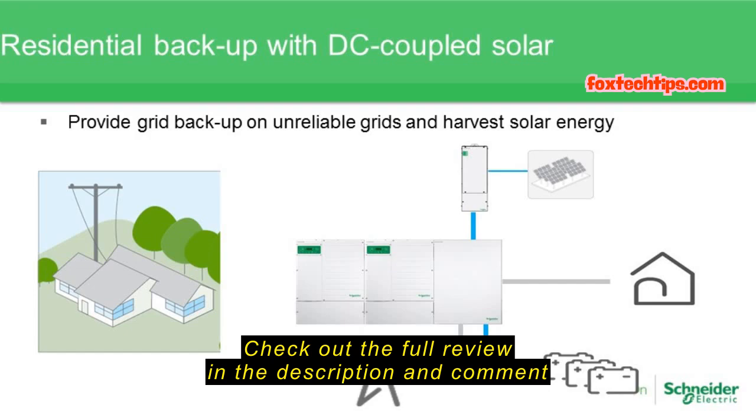From that power distribution panel, we can land our conductors for the grid, for the batteries, and for the backup power to the home. For that home symbol, there would be another little box there that is your critical load panel. In some places, let's say in Australia, they only have a 50 amp panel. And so it's very reasonable to think that putting the entire home onto the output of the inverter could be done. But again, there are some risks that come with doing something like that, because there are potentially some very large loads that the customer may not be aware of during a power outage.